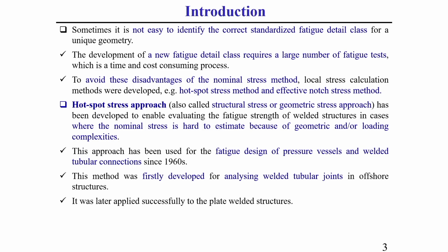Sometimes it is not easy to identify the correct standardized fatigue detail class for a unique geometry, because in the nominal stress approach, according to IIW, some standard classes are available from which we find the FAT value, which is generally used to determine the fatigue life of a structure.